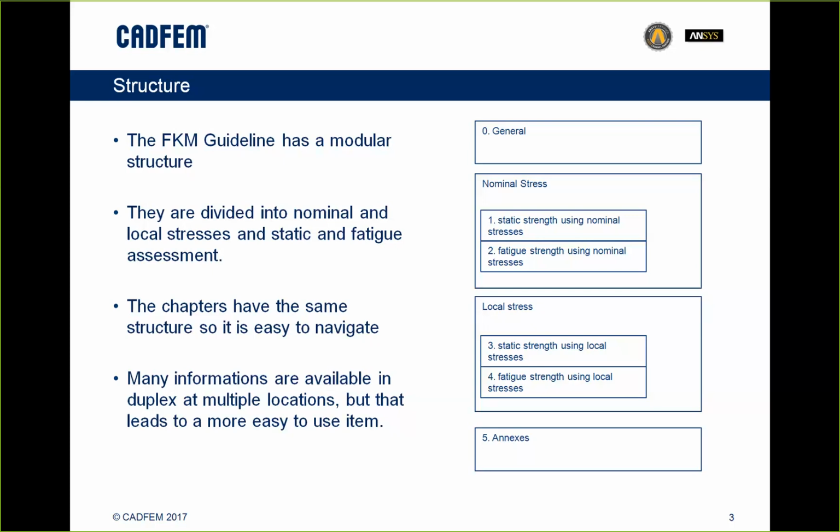If I have an S235, I know the yield is at 235 megapascal. I know also the ultimate is at 370 megapascal. And if my stress is now at 200 megapascal, I know it will not yield. But if my stress is at 200 megapascal and it's a pulsating one, I'm not so sure if it will have an endurance, if we are below the endurance limit. So if I could survive this stress load indefinitely, or if we just have a certain amount of cycles left before my part will fail.